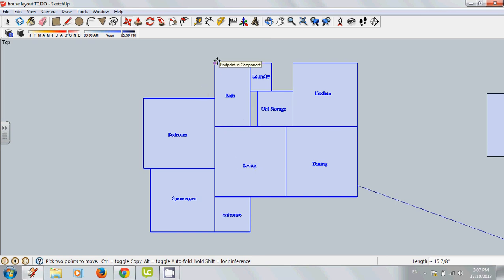The other thing we want to do is try and make the house as rectangular as possible, because any change in the walls, any little bumps like this are going to cost you more money. So in this case, I would probably extend this and make it square. I would definitely extend this over here and just have the wall go through. You could have a little porch over here, so you might just leave that, and you might have a porch across the front. So your roof system could be very simple on this type of house.